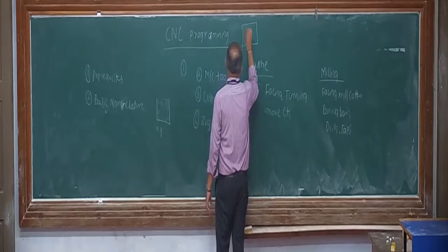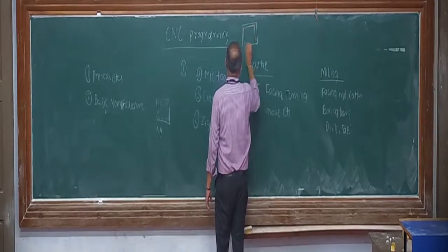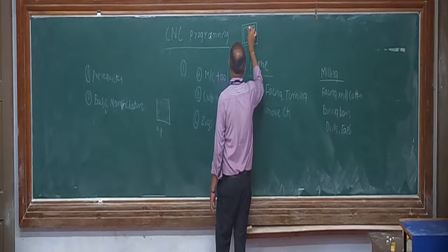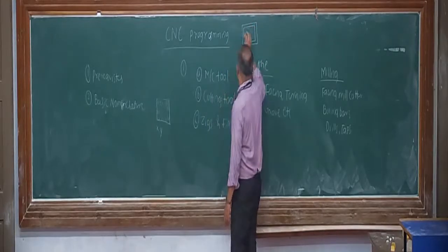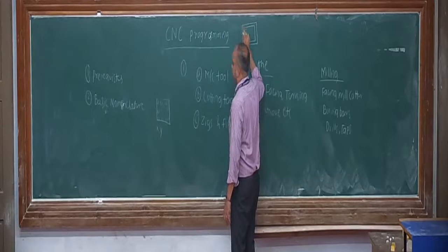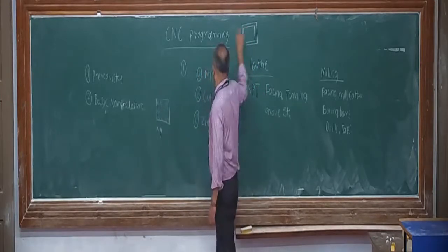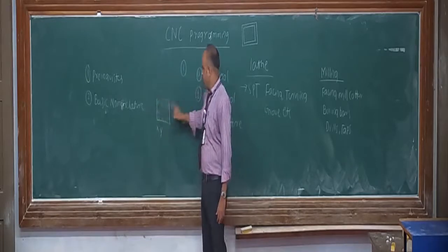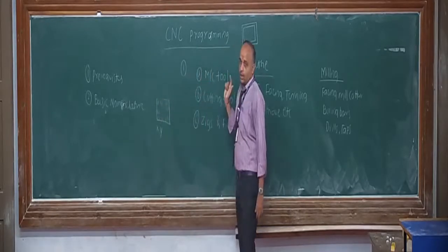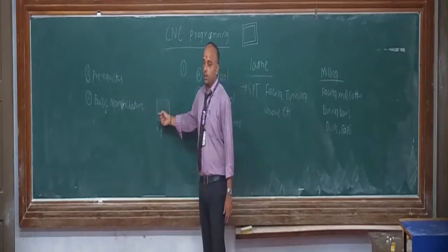A jig is nothing but a plate. Remember, we usually use a jig on a drilling machine. We do not use a jig on a milling machine. In case of a jig, we create a template which will have similar positioning. I put this plate on the workpiece, and wherever the holes are, I directly go on drilling, so that we do not measure the quadrants.